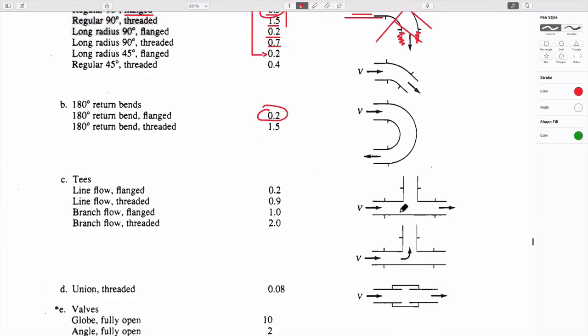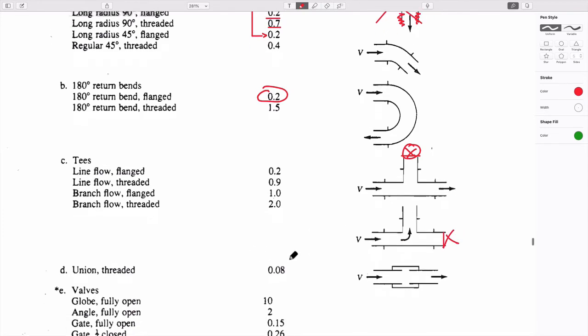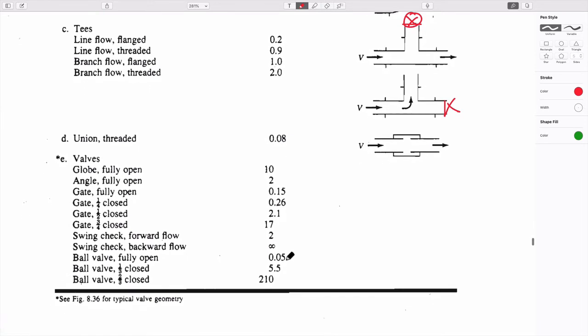And also in going through other fittings. For instance, even if you go past, even if there's no flow in this direction, because maybe this is capped off, or maybe there's a faucet on here which is closed, there's a loss that you go across this boundary, which you can imagine, and it changes depending on the forms of the fitting. And if you actually have this capped off here so that the flow is around this bend, then you can calculate exactly what those would be as well. If you have a connection, as we said before, as a union,